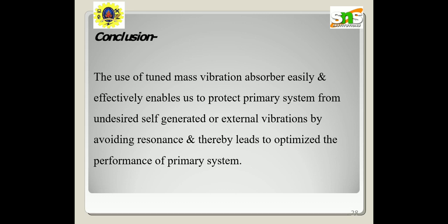The tuned parameter of the tuned mass damper enables the auxiliary mass to oscillate with a phase shift with respect to the motion of the structure. In a typical configuration, an auxiliary mass hung below the nacelle of a wind turbine is supported by a friction plate. So this is a case study for the design of a tuned mass damper. These data are collected from Star Trace Private Limited, Chennai.